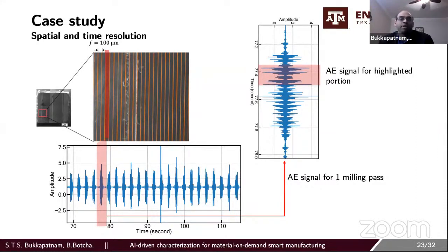If you look at the vibration data as well as force data, they will probably be submerged within the noise bands. But acoustic emission luckily will be able to capture it. But as you correctly said, the energy levels will be so low that you need some advanced processing to extract useful information out of acoustic emission.